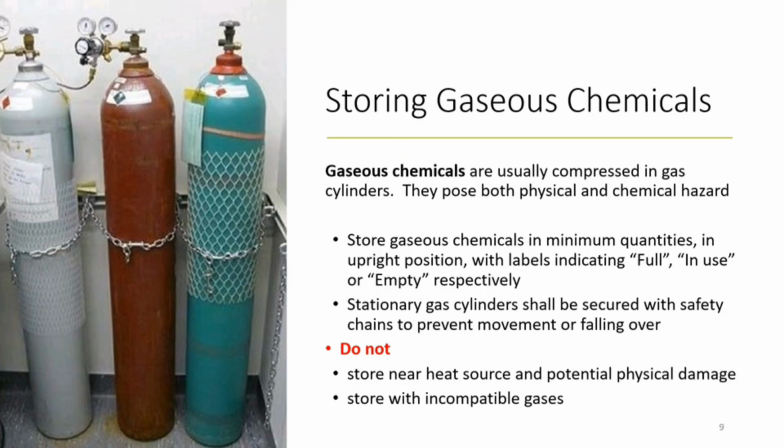Do not roll or drag the gas cylinder, as this can cause damage to the cylinder, leading to leakage of the gases. Do not store incompatible gases together, for example, oxygen and fuel gas.